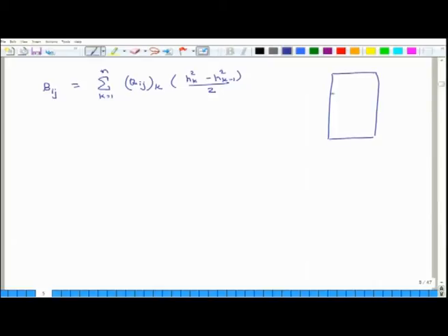So, there are 2 layers, this is the mid plane. So, z is equal to 0, this is h0. So, this total thickness is plus 4 to minus 4. Here z is equal to 4 millimeters, here z is equal to minus 4 millimeters, here z is equal to minus 1 millimeter. So, in this case there are only 2 layers. This is the 45-degree layer and this is the 0-degree layer.